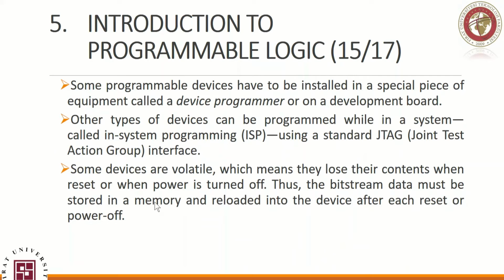All right. So I spoke about the programming process of those. We have just one final piece. This is a very specific topic about how we can exactly program the device. Do we need to fit it on a development board for programming, or do we need to use something we call in-system programming, ISP, or the standard JTAG, the Joint Test Action Group? These are a bit advanced topics.